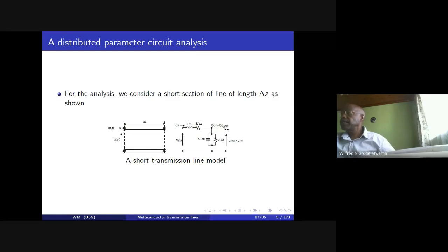the section at the point z plus delta z, and a voltage across there which is Vz plus delta Vz. Therefore the total conductance is given as G prime multiplied by delta z, and the total capacitance is C prime multiplied by delta z. So this is a model that you have already covered in ECT, and we can see that whether we are using electrodynamics or ECT, we are just talking about the same things.